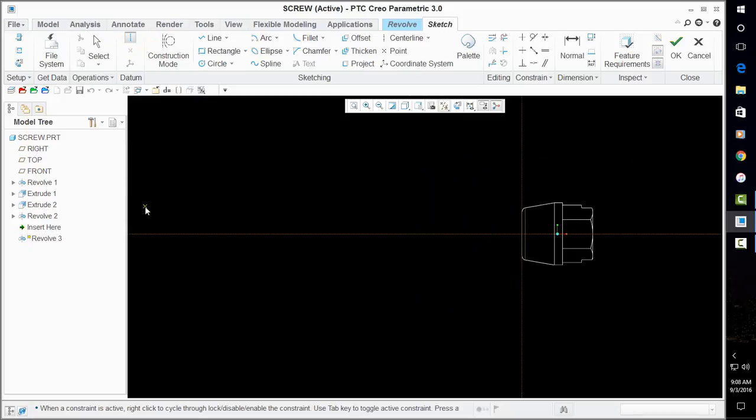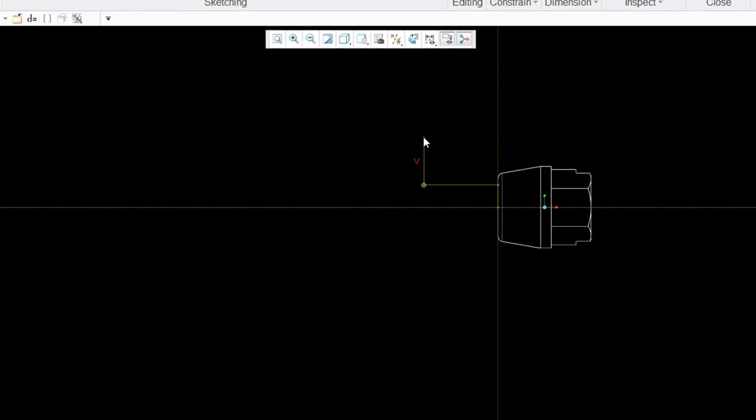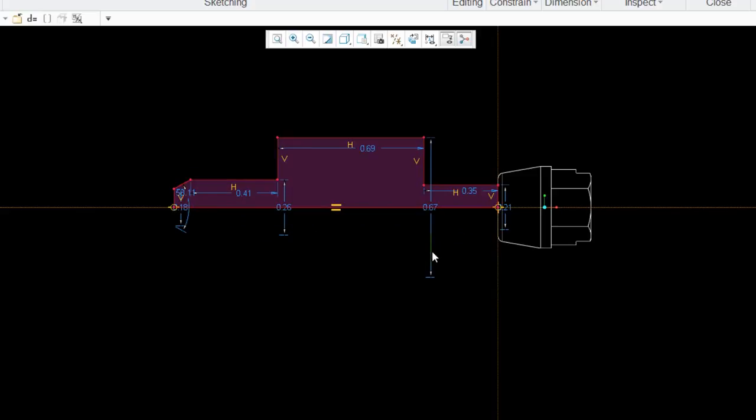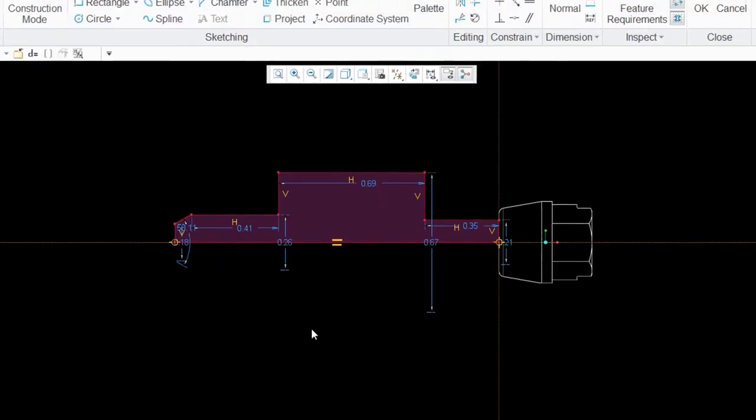Center line first. And we're going to have a line that's going to come from here up to here, over to here. We can put this out of scale if you want to. It doesn't matter. We're just roughing this in. Don't let it snap to any of these things. It tries to snap, don't let it snap. Just pull it until it doesn't. And come down and over. Don't let it snap to any of that stuff. There's a little angle down, and let's close it up. So we have a closed section now.